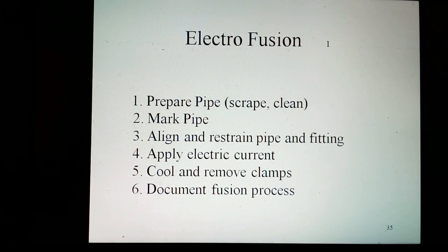Step 5. Cool and remove the clamps. Allow the joint to cool for the recommended time. If using clamps, premature removal from the clamps and any strain on the joint that has not fully cooled can be detrimental to joint performance. Consult the fitting manufacturer for detailed parameters and procedures.